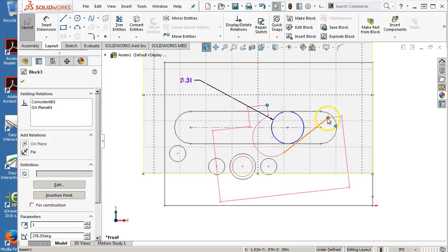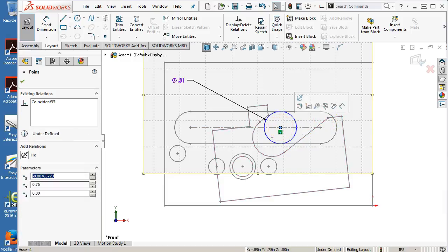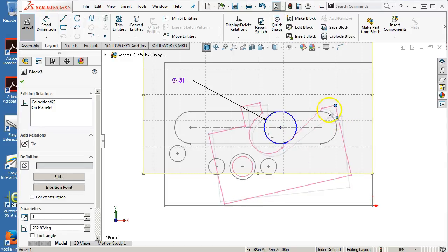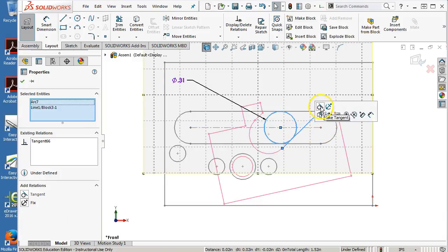If you hadn't set that 45 degrees, would that solve that? Well, the dimensions at this point, the dimensions are driving. So the 58 degrees, that's something that needs to be resolved. Yes, the 45 degrees has precedence over the 130. So the number that I'm not sure about was the center point distance from here to here. Oh, that's cool. So you can make a tangent and drag it around. Exactly, we can go ahead and set those relations.